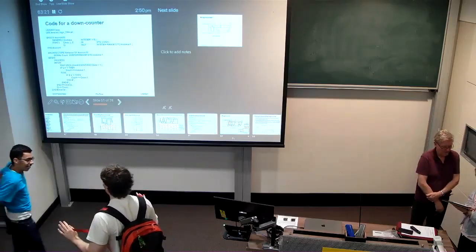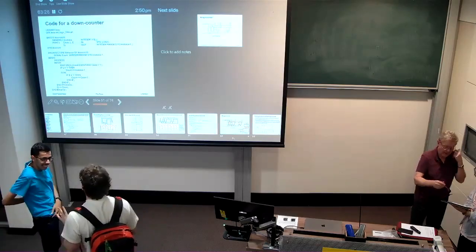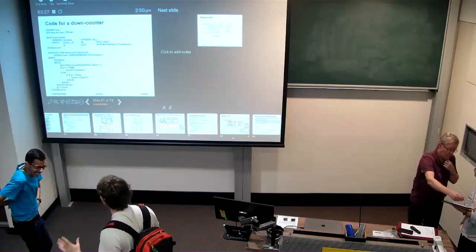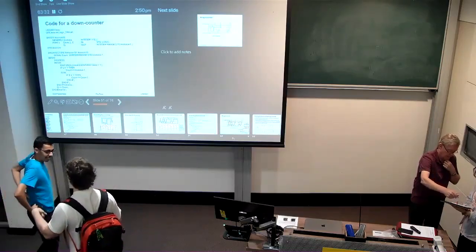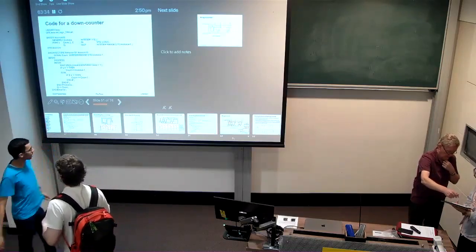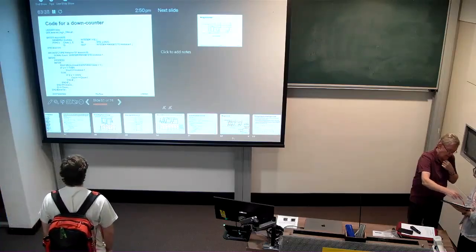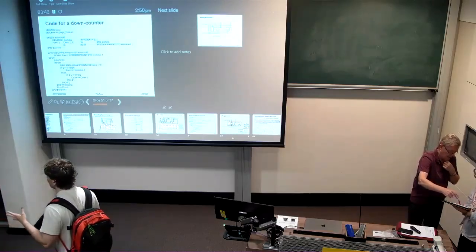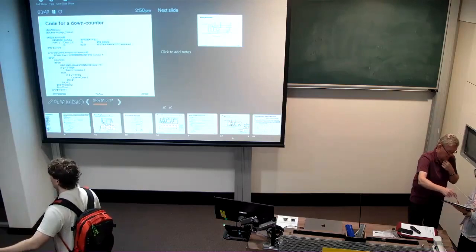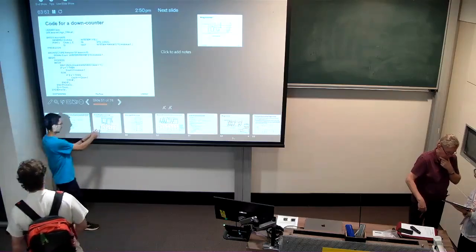I'm exploring additional processes in the concurrent thread. Now, the problem is that it takes time between the clock going high and P2 going to 0, a delta concurrency time. If D changes immediately after the clock changes, it's possible for P4 to change before P2 goes to 0. That's what the timing diagram shows.